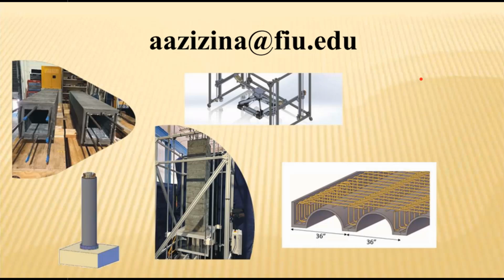Okay. How is the mechanical linkage achieved between the precast shell and the fresh UHPC fill material? If you have a hardened UHPC and you want to cast normal strength concrete and get complete composite action, the only thing is to physically have something inserted into the UHPC shell that's hardened. That's the only way to get it all the way to the end. Other than that, no. You cannot rely on fresh normal strength concrete or fresh UHPC cast against the hardened UHPC.